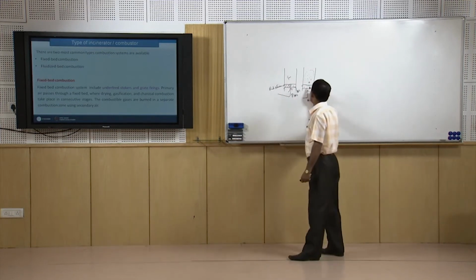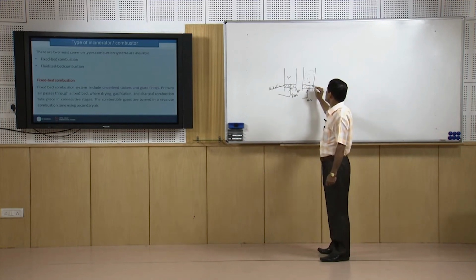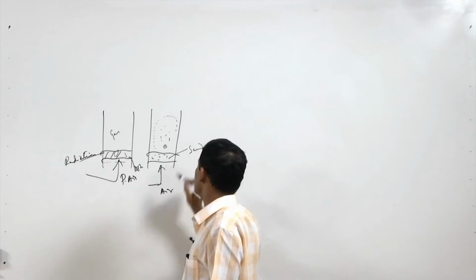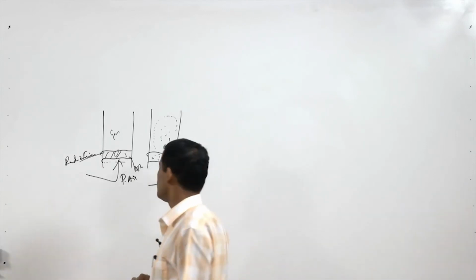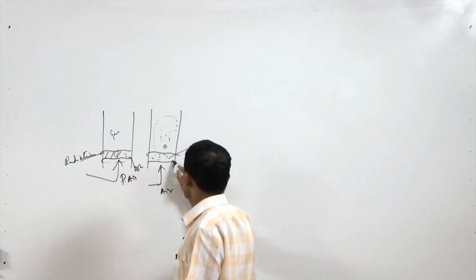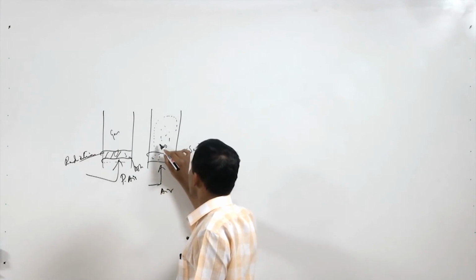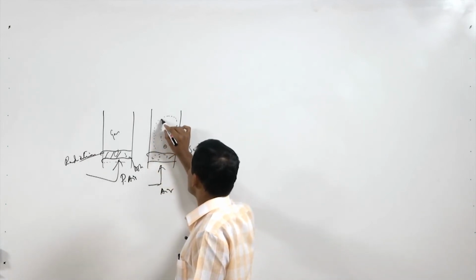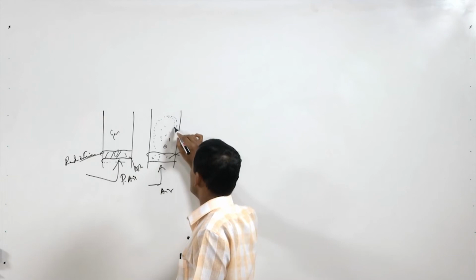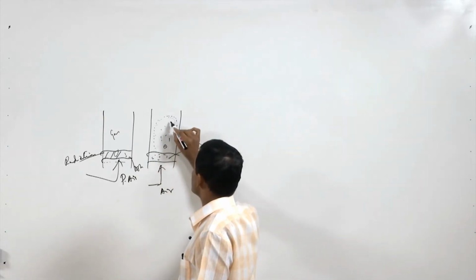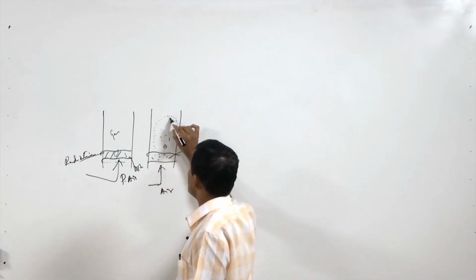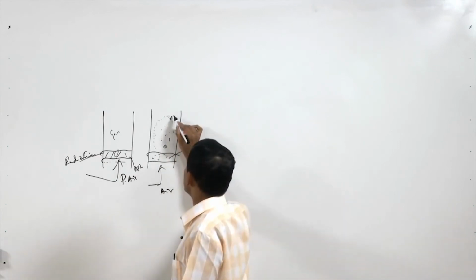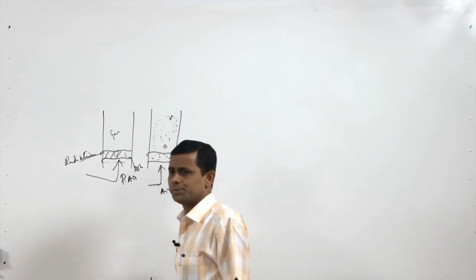Here we need to provide some media, basically sand. So, the sand media is used here and it is heated up. That sand media and solid particles are in fluidized phase, and this hot sand media transfers heat to the solid biomass or solid waste.